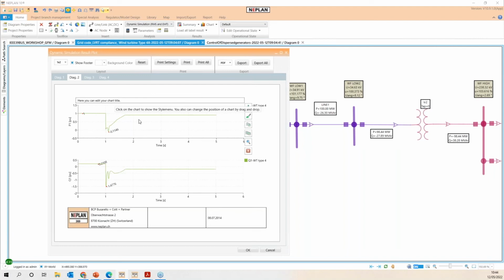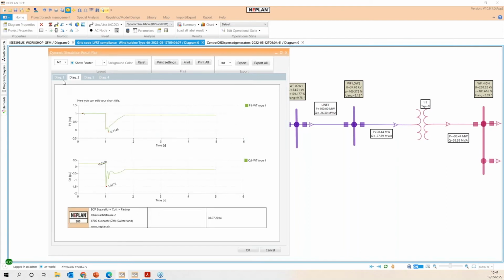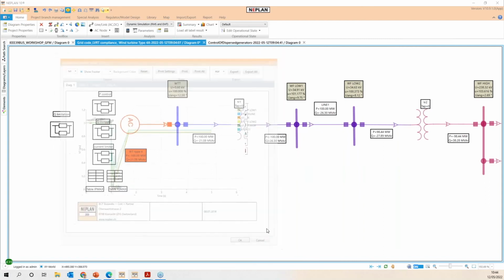The low voltage ride-through specification here should meet the specification of the grid code compliance, and we are able to supply or support these validations if they are inside the limits of the grid code requirements. Again, the control signals can also be specified during the dynamic simulation.